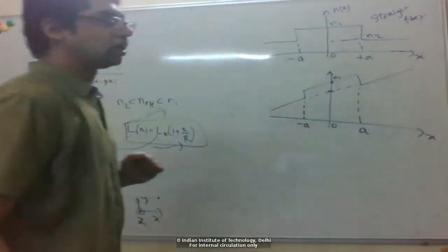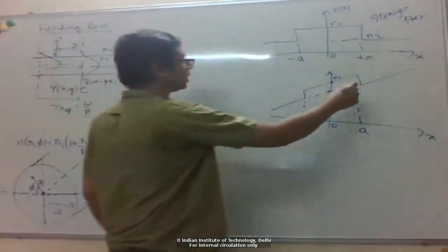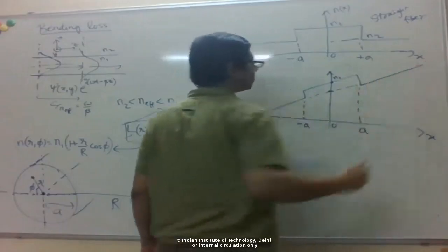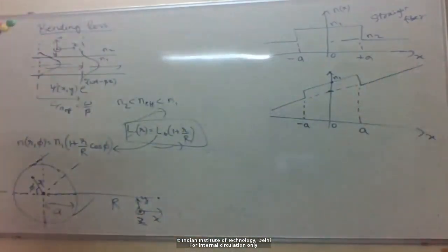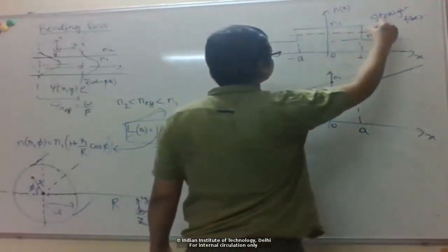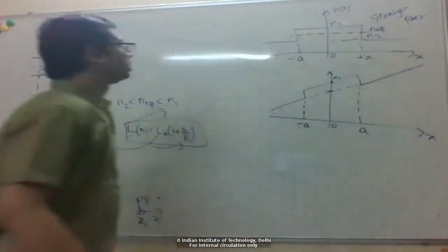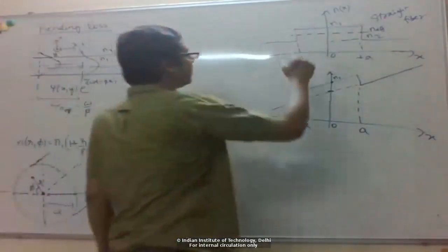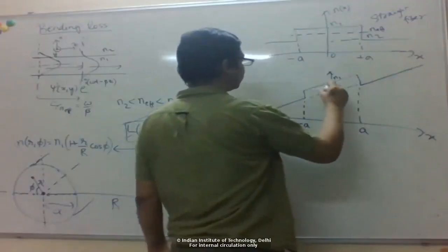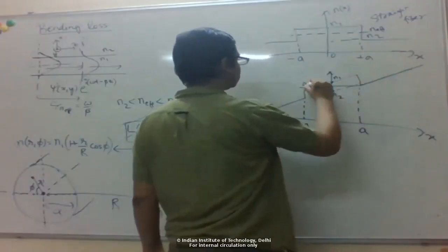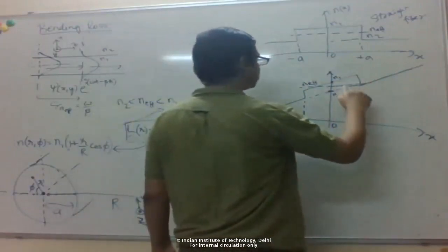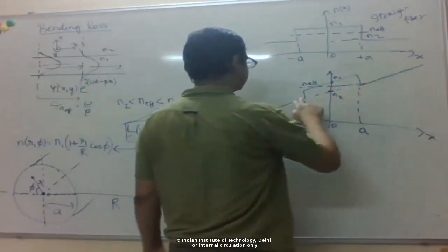To see the effect of the bend, we need to solve for modes in such a refractive index profile. You can see this looks like a weird profile, because this index here keeps going up. For example, in the straight fiber, we solve for a mode and get some n effective, which is typically somewhere between N1 and N2. So let's say this is N2, and the n effective will lie somewhere here. I should make this a bit bigger.